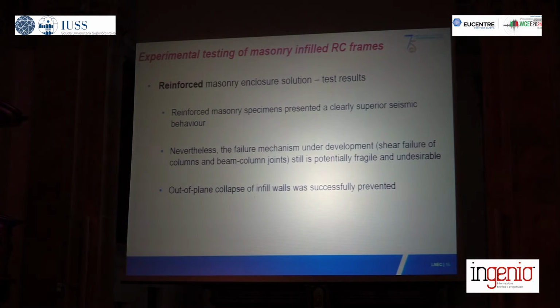So this reinforced masonry specimen has presented a clearly superior seismic behavior, but nevertheless we have a failure mechanism which is under development, is still potentially a fragile one and an undesirable one. But the out-of-plane collapse of the infill walls was successfully prevented.